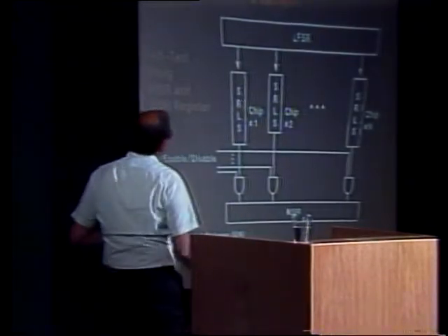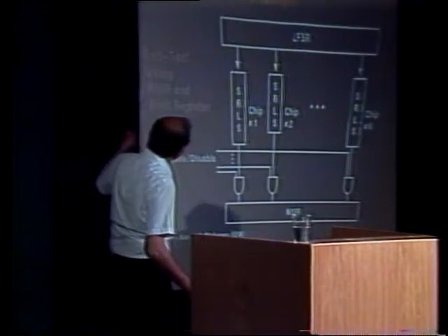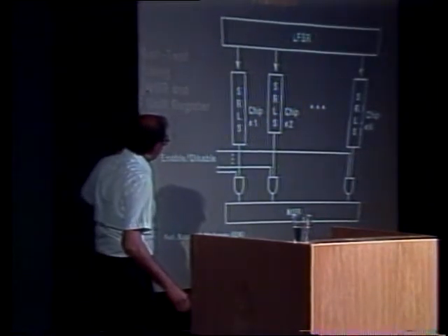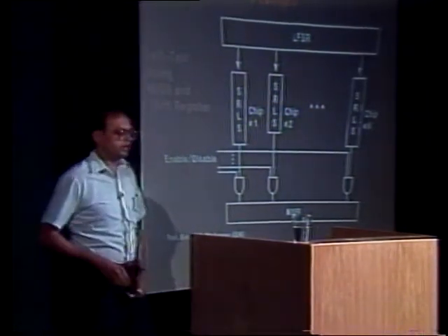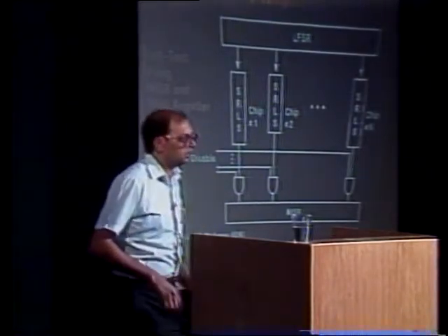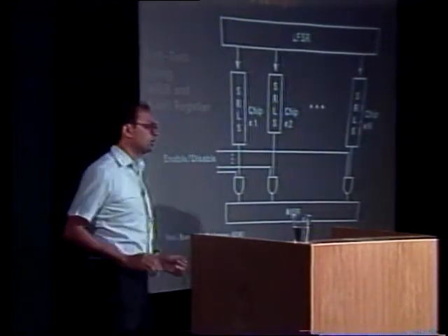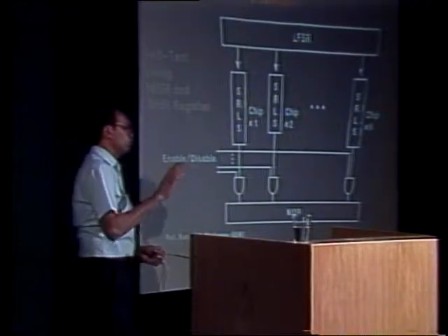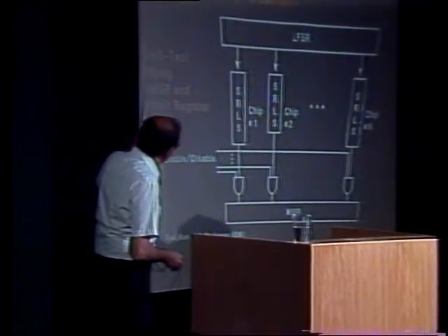An extension of this idea, IBM calls STUMPS, which stands for self-test using MISR and shift register. I think Roy forgot to mention to you that in this field, there is ample opportunity to give names, okay? That PolyDiv was one instance of that. Now here is STUMPS.